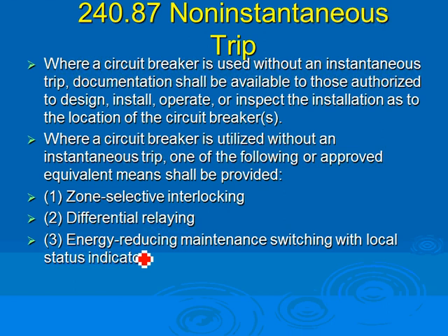Like I said, everybody knows series rated ones. Why do we use series? There are two types of systems, guys. There are fully rated circuit breakers, which we use in power, switchgear, switchboards, and so forth. And the series rated, we use in receptacle panels and lighting panels. The reason we have series rated is that the equipment is cheaper. When you have a 30 amp circuit breaker rated for 10K, say this circuit breaker is $100. If it's rated for 225 amp, 22,500 amps, that will double or triple the price of this circuit breaker, because it has to be more robust to handle more short circuit.